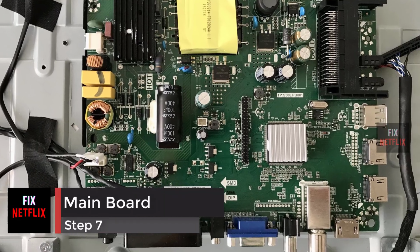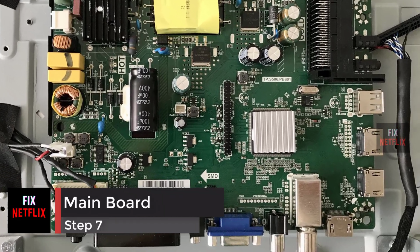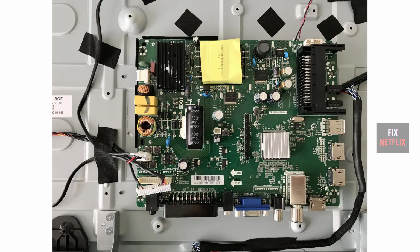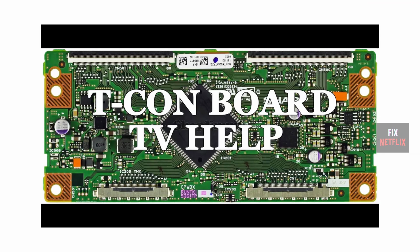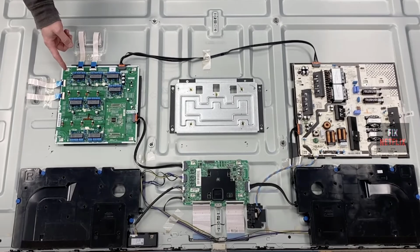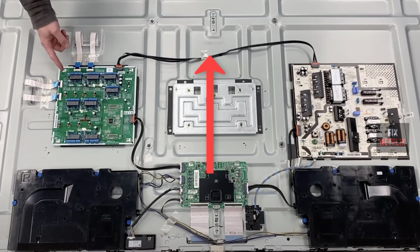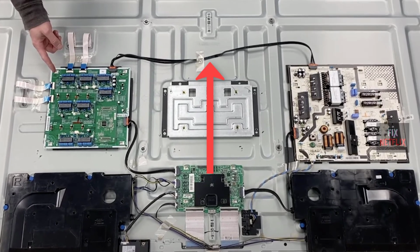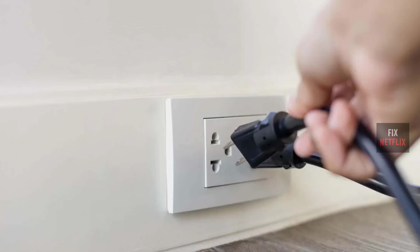Step 7. Main board. Now we check the main board to see if it is the culprit. If a problem shows up on half the screen or only a portion, it is likely the main board, rather than the TCON board. Make sure the TV is unplugged. Plug in the cable running between the power board and the main board, which was disconnected in the previous procedure. Then plug in the TV.